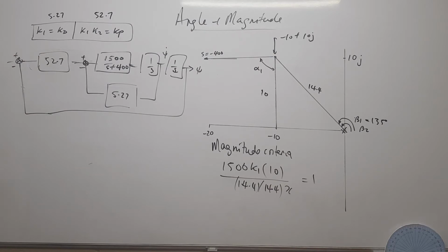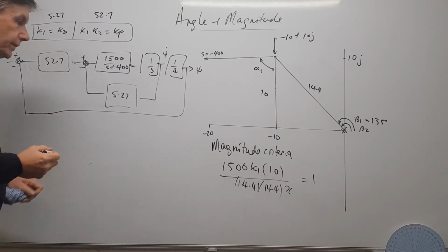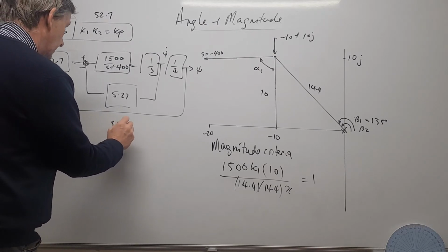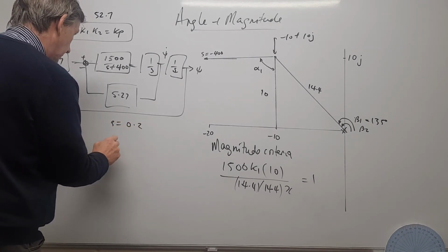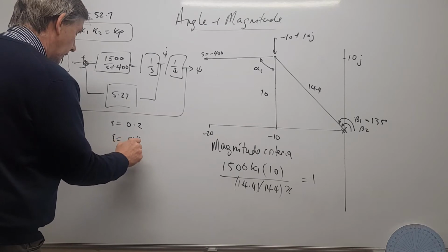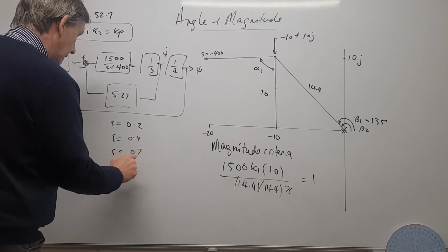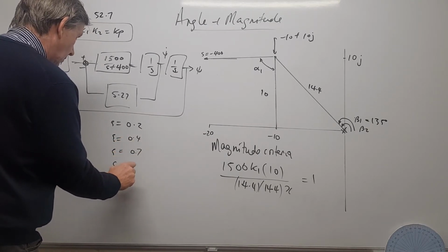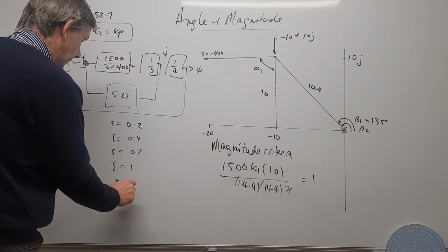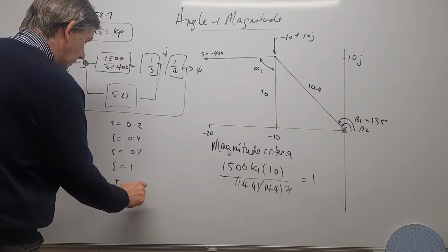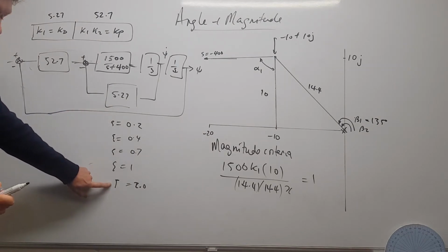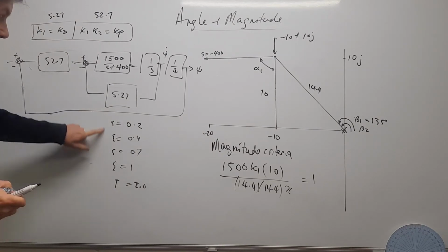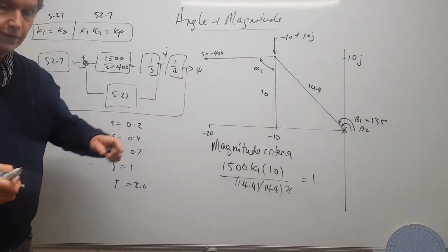And what we're hoping to do now is have a range of damping ratios, say all the way from about 0.2 up to damping of 0.4, 0.7, 1, even bigger than 1, say 1.2 or something. So we'll have it very lightly damped all the way through to very heavily damped, and then look at the performance of the drone as it actually flies.